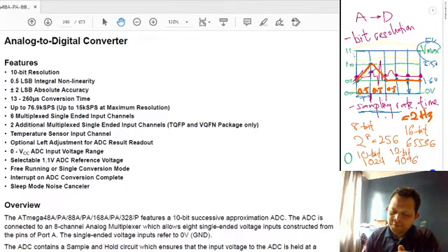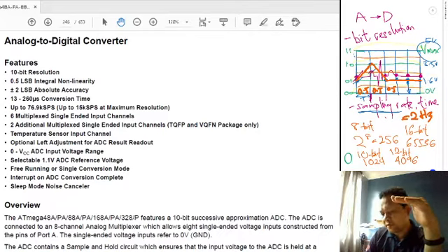Because when you have higher bit resolutions, you have more voltage levels, into which your 5 volt will be broken down. Just now we broke down into 4, now into 8, and then into 16 levels, then break down again.